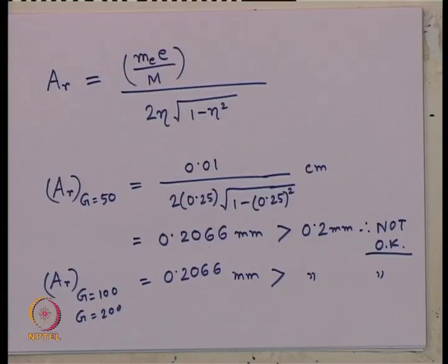Okay. So, for rotating mass type, the same block type of foundation in all the three cases of soil, at operating frequency they are perfectly fine, because the displacement amplitudes are within permissible range. However, at resonance frequency it is not okay for all the three different types of soil. So, with this we have completed only the analysis for vertical mode of vibration. Now, let us go for next mode of vibration, which is sliding mode of vibration.